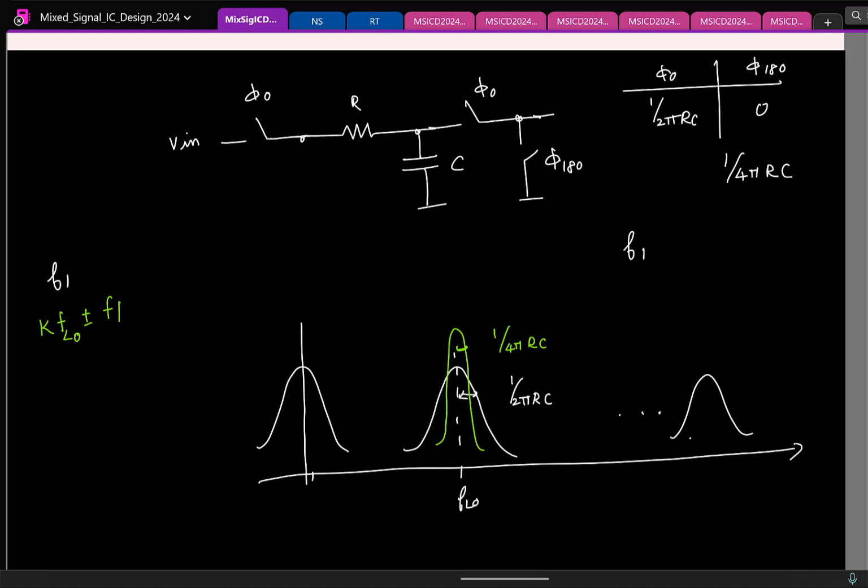Your statement is correct, but the inference is wrong. Remember, if I make it infinity, what happens? Aliasing is coming from infinitely large frequencies, so it's okay. You sample it faster, you are preventing aliasing. Okay. But now if you keep increasing the frequency, the switches will be difficult to design.